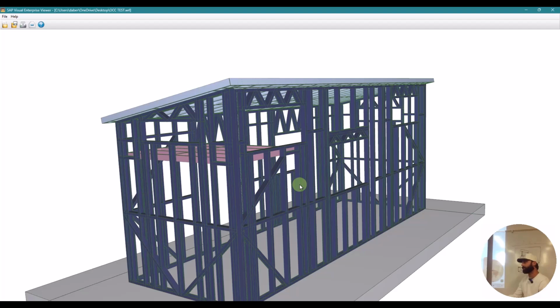One of our engineers is really good at incorporating structural steel and HSS with the sheathing, with the strapping, with other structural components involved. We're advocates of FrameCAD, but one of the limitations of the FrameCAD structure software is you can't incorporate third-party materials outside of the steel to make sure you're exceeding local load requirements.